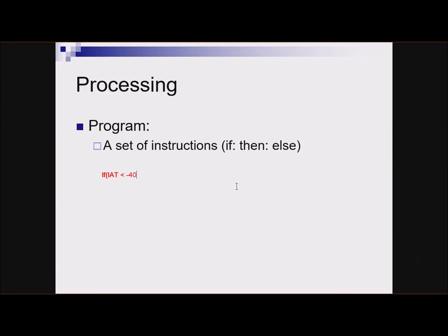So if the intake air temperature is less than, say, negative 39, then turn on the check engine light. Else, turn it off, or leave it off, right?